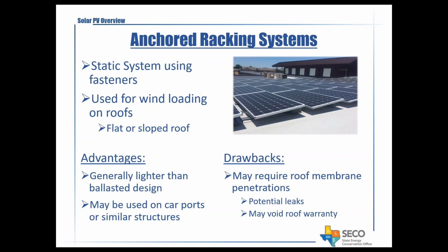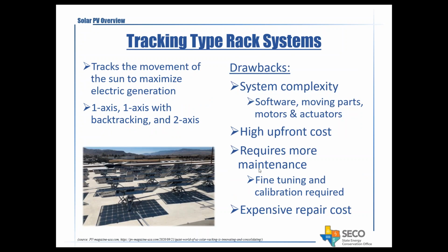And there's a possibility of the penetrations voiding the roof warranty, but that just needs to be looked at or considered during the design phase. If you have roofing consultants, then they should be able to help with that. Or if the roofing contractor performs the work, then it may be okay, and there may not be any issues with the warranty on that.